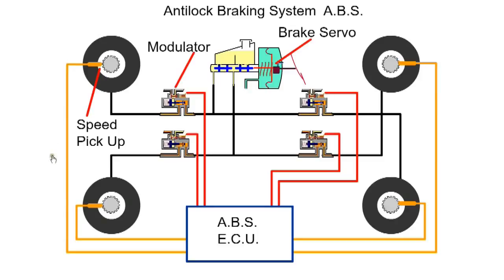Wheel speed is detected by a proximity sensor located beside a toothed wheel which sends a signal to the ECU. Between the master cylinder and wheel is a modulating valve. Imminent wheel lock can be determined by one wheel decelerating at a higher rate than the other 3 wheels, or a wheel decelerating at a rate which is physically not possible without locking up.